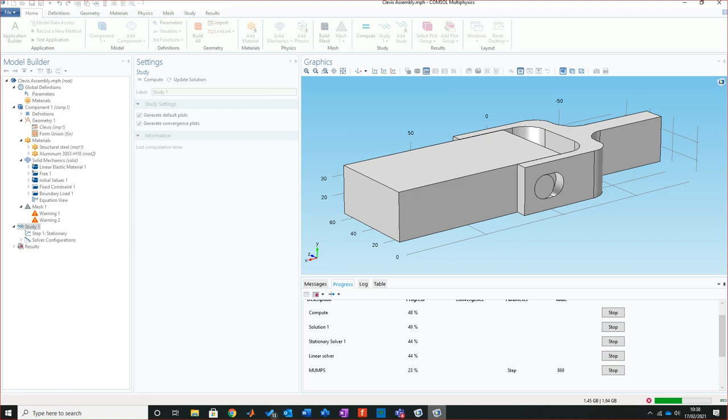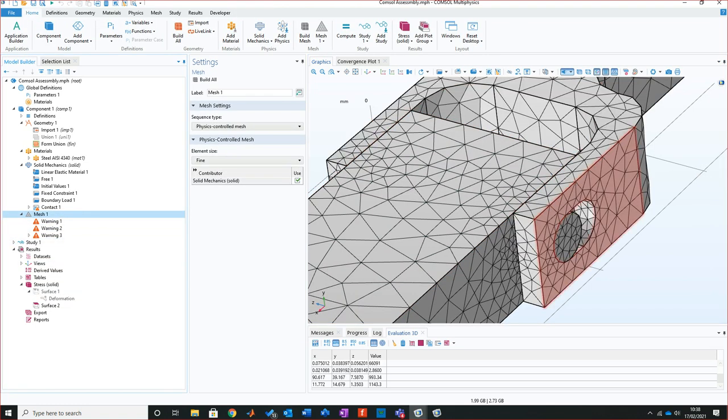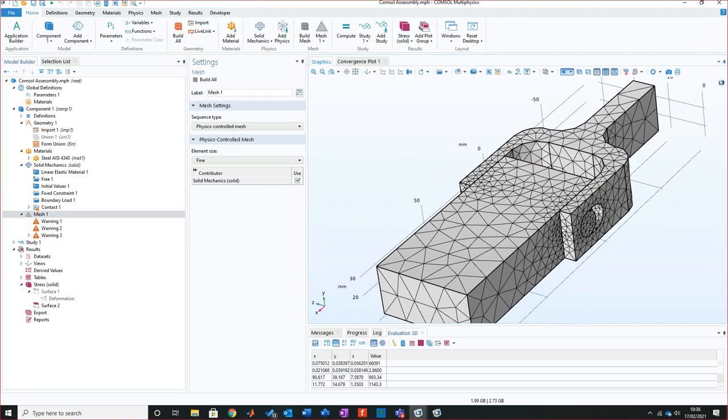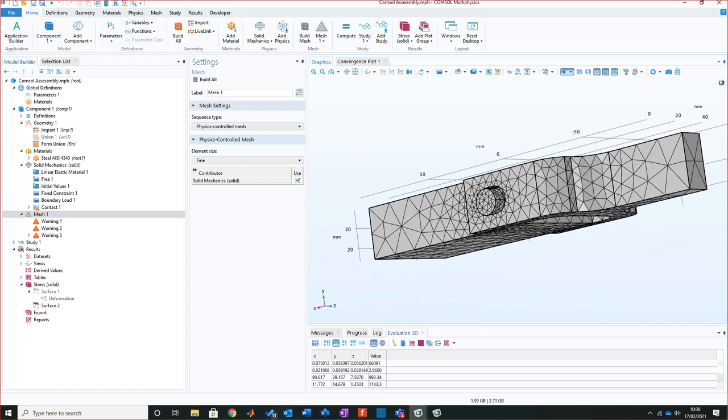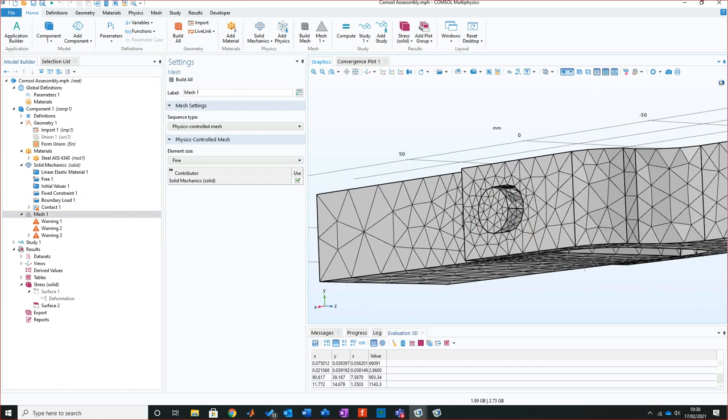What I would like to do, though, is look at, has that even solved yet? I would actually like to look at the refinement of this meshing. You look at my mesh, it's still that little bit clumsy, still that little bit awkward, and what I would like to do is refine that. It's because I'm not convinced using tetrahedrons on that area is going to do it.